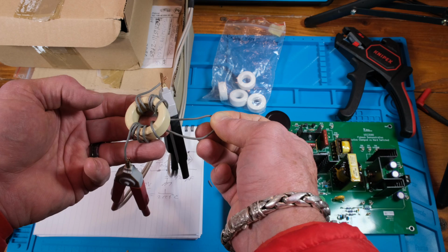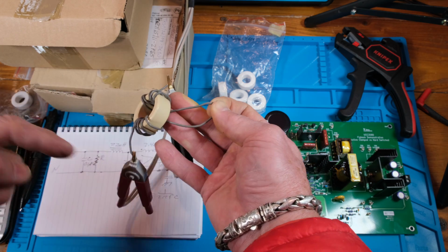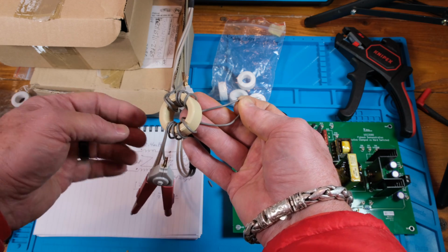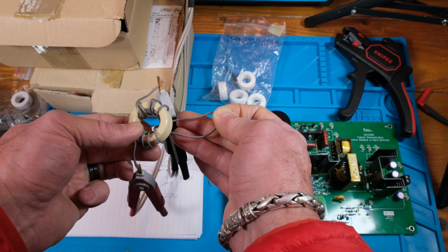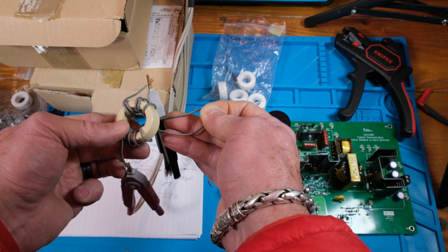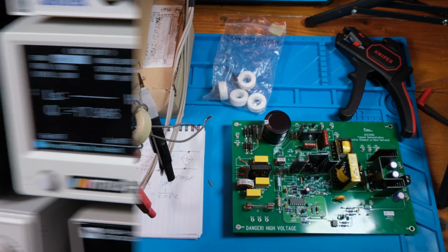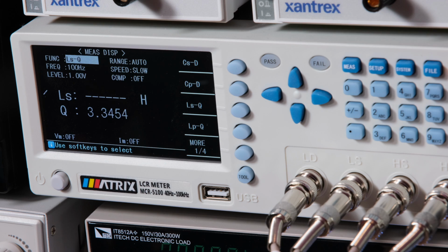They're in series. And when you're connecting in, where the current goes through the circuit, out the other circuit like it is now, okay? So the current comes this way, goes through the circuit, comes back this way. That's differential. We're about 2.4 microhenries. So it's about the same as when I shorted it, right? And it should be. All right, I'll give you a view of the meter up there. Okay, now this is when I connect them together in common mode. See, it's about 2 microhenries, okay?